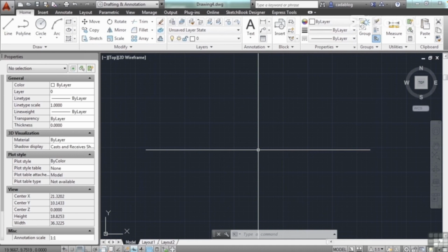Well, let's say now all of a sudden the client has a special request and they want one that's 36 inches. Well, now you've got to make a third block. And then now let's say, well, you know what? All those 36-inch doors, I want them to be 34-inch doors. You have to change them. So you have to delete them all, reinsert them. That's some extra work. But if you had a block in there for that door that was already a dynamic block, then you could design it so that it would fit all these needs, but with just one block. That would help you to make the changes very quickly. It also makes these blocks more useful since one block can fill many needs.